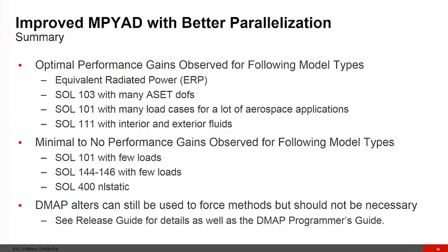This is where you see a lot of gain in performance. And we have added this for solution 111, modal frequency response with interior and exterior fluids. It was not very significant for solution 101 with few loads, or solution 144, 146, or for 400 NL static.